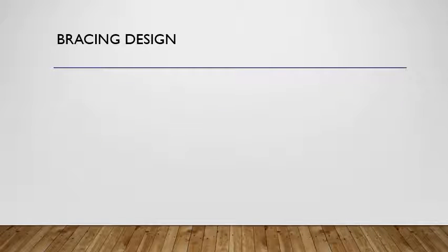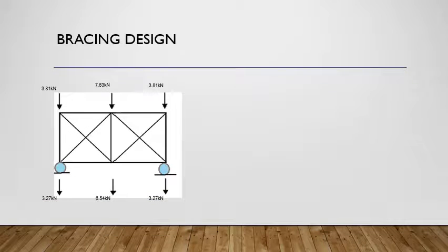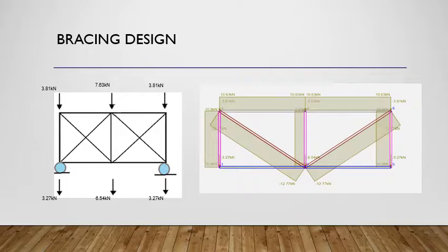For truss analysis, all the support reactions and member forces were determined by Spacegass. The diagonal members only resist tension. Thus, we need to remove the compressive diagonal member based on the position of the load applied. All the support reactions and member forces were determined by Spacegass.